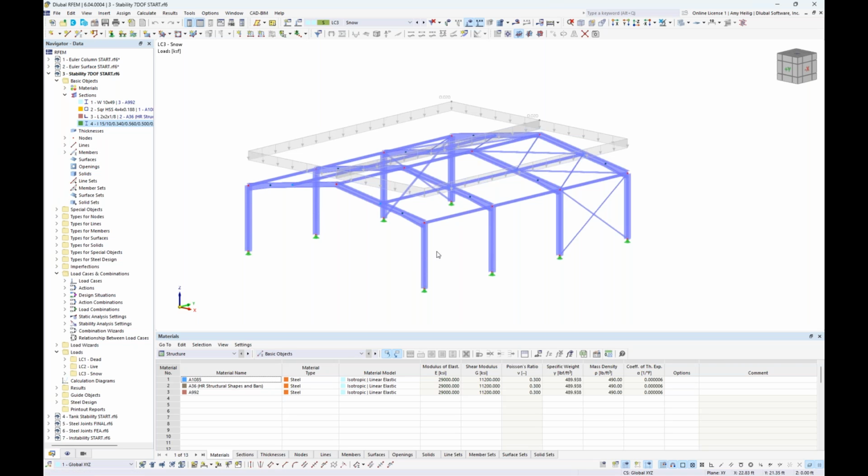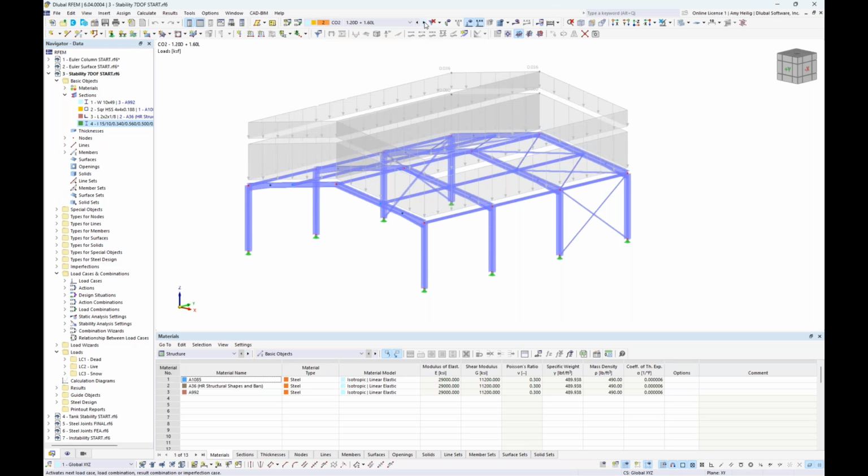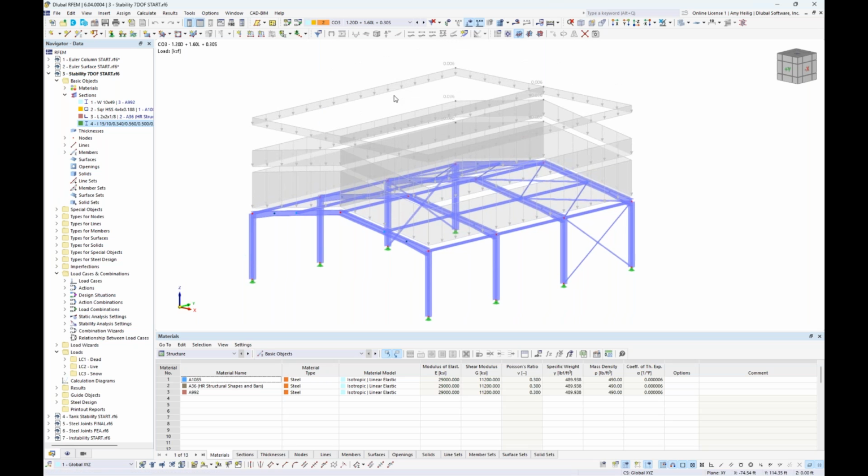If we were to include, let's say, wind uplift forces, this is only going to do us additional favors in terms of the buckling behavior, because now we have introduced additional tension forces in those members. So again, when we are evaluating the structure stability, we really want to look at those downward compression, possibly gravity only loads. Okay, so I have additionally combined these load cases into load combinations according to the ASCE 7, and we can see those displayed here graphically along with the relevant load factors.